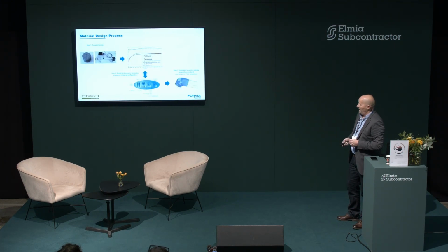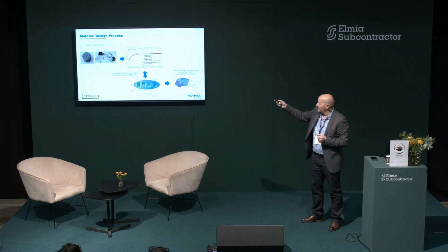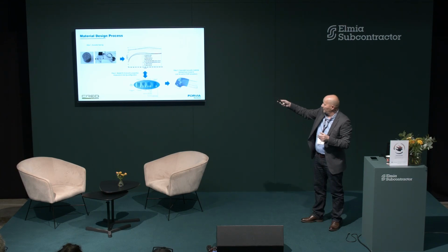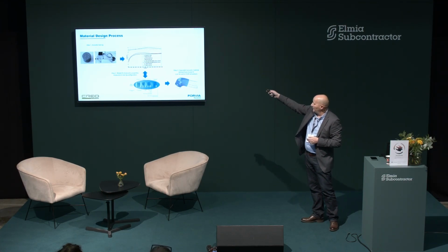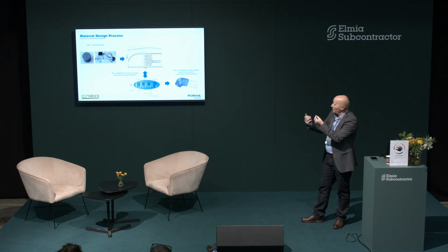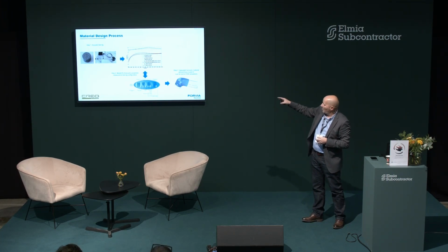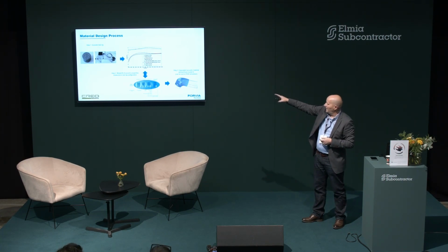performances. So the way you can link these two approaches is to start with this measurement in a rig, which is in a controlled environment, and to get some acoustic parameters. Here, this is an impedance curve, which is a description of the acoustics of these materials. And what we did was to use this model in this simple configuration to fit the measurement.